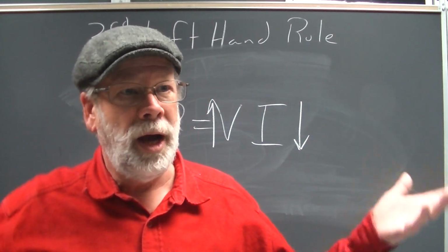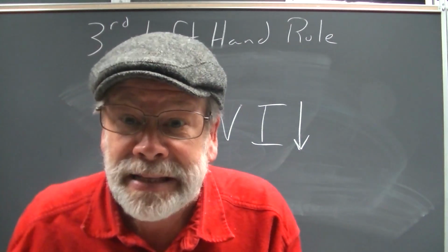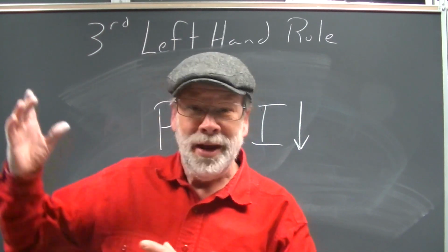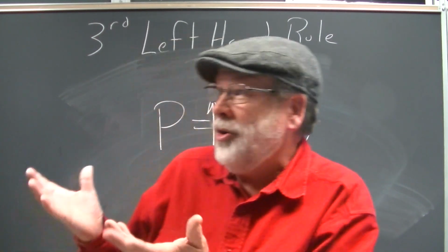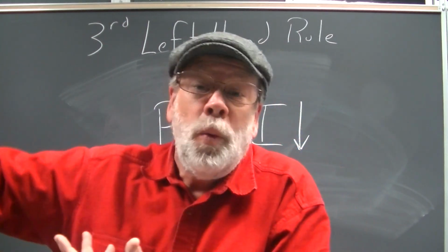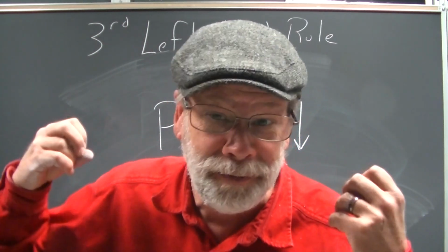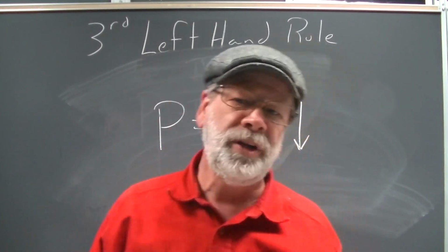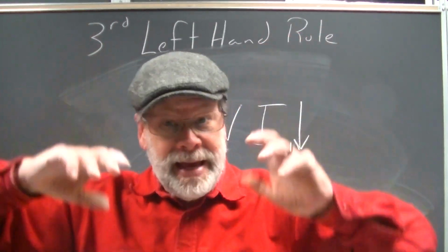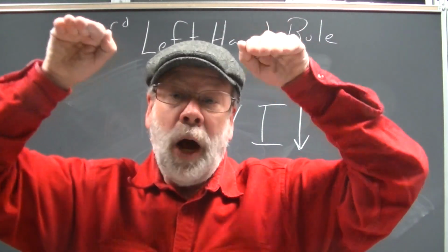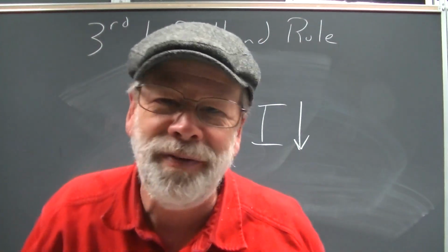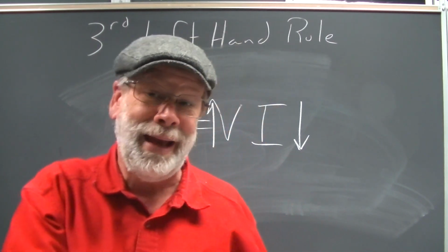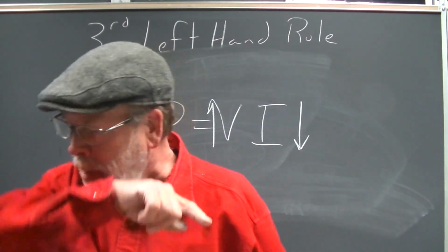Now, high voltage, is that dangerous? Yes, high voltage is really, really dangerous. Why? Well, if you have a really high voltage line near you and you're even standing next to it, you can arc right through the air and fry yourself. Well, take a look at those transmission towers. The higher the voltage, the bigger the towers, the more they keep those lines away from everything. Those lines don't even have insulation on them because it wouldn't really matter. That arc would go right through that insulation if you got close enough.